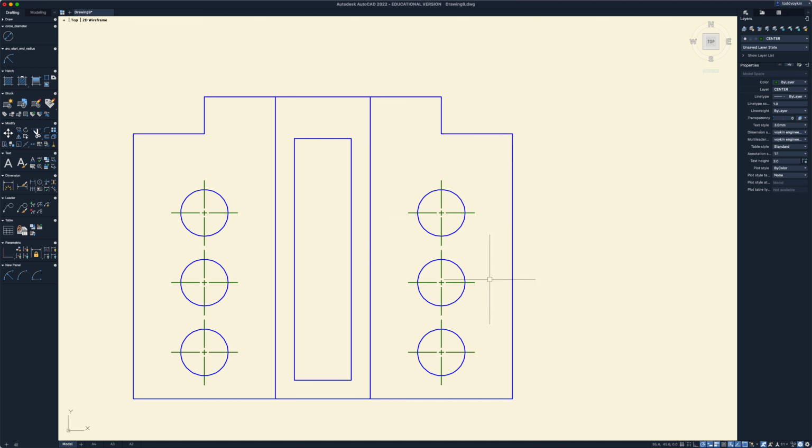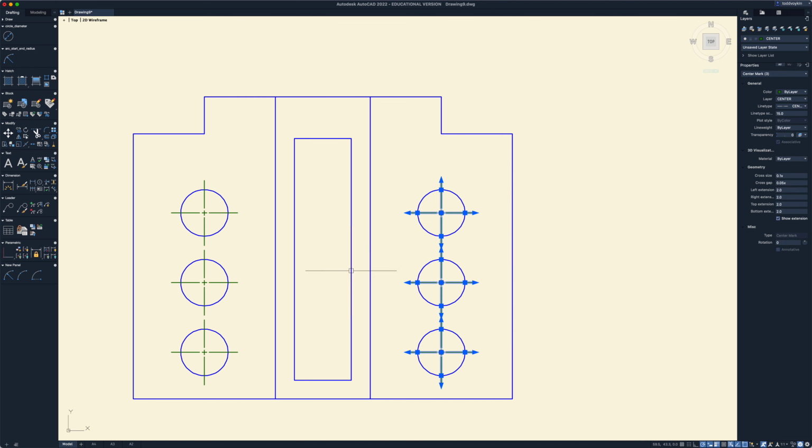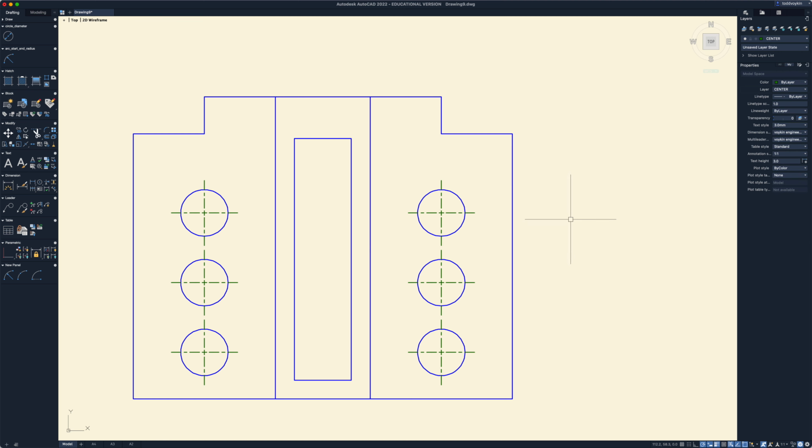And now you can see when I change that to 15, I should be getting that same line type where I see one dash, which is long, followed by a shorter dash. So that was a little bit too much, so maybe I'll go to 5, and there we go. That looks a lot better. So you can see I've got the short dashes and the long dashes, and I'm extending past there.